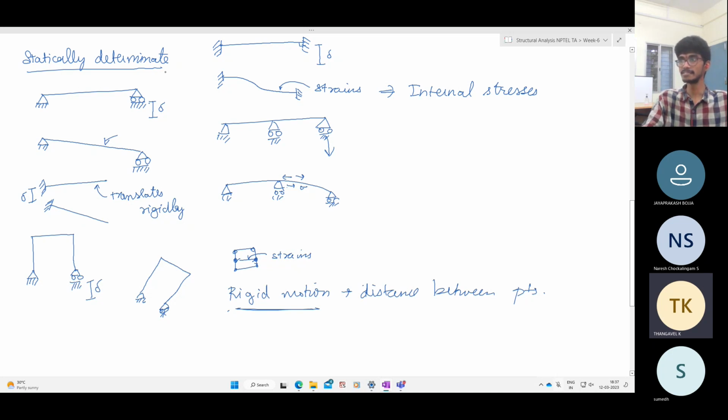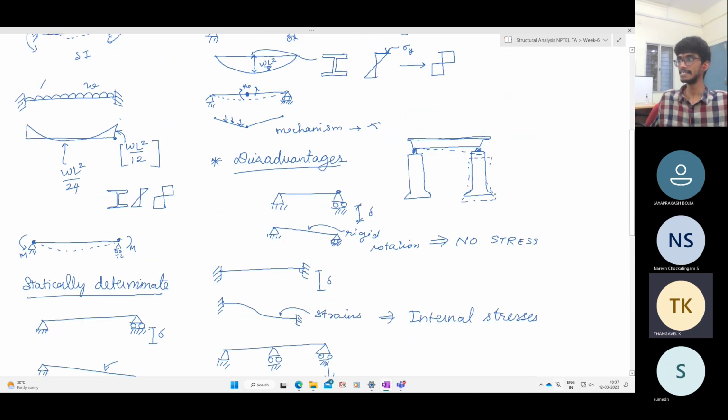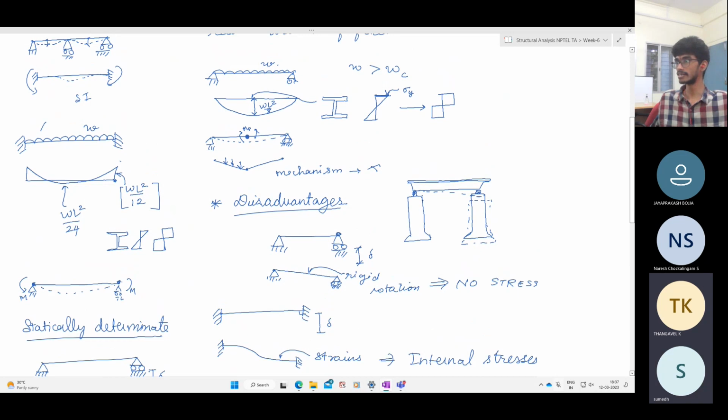So in statically determinate structures, no strains can be induced by a sinking support. But in statically indeterminate structures, they are generated. That is why, even today, while all our buildings are statically indeterminate to a very high degree, most highway bridges are designed as statically determinate structures. That's what I drew here. They are all simply supported. The bridge deck is simply supported on the pier. And to ensure it is actually simply supported, they don't put it directly on it. They put it on a small bearing so that it allows free rotation.